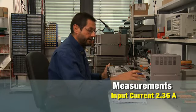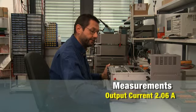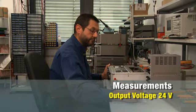The input current is 2.36 amp because we have set an output current on our load of 2.06 amp, and the output voltage of the module, it is a 24 volt output, and we read exactly 24 volt.